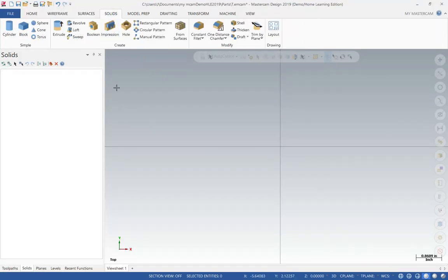And in solids, there are a couple of ways to do that. You can either import your 3D models from CAD, Inventor, or SolidWorks, or you can draw it in here. But if you do import the drawing from SolidWorks or Inventor, then you lose the associativity. So your toolpath cannot be updated in here. Or if you just edit the drawing, you will have to re-import the drawing again. But if you do that in here in MasterCAM, everything is associated. So you don't have to recreate the toolpath or re-import the drawing.